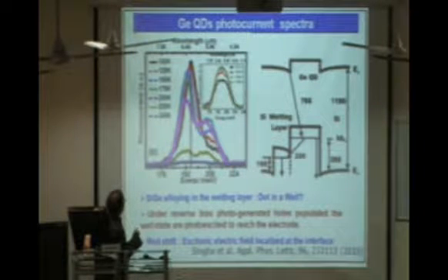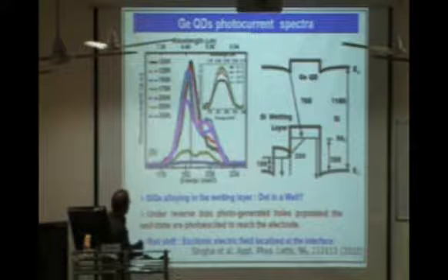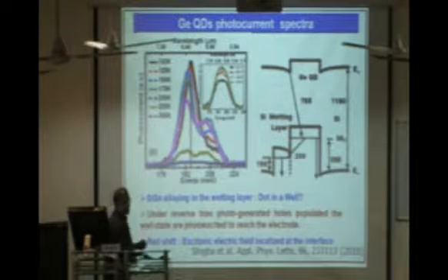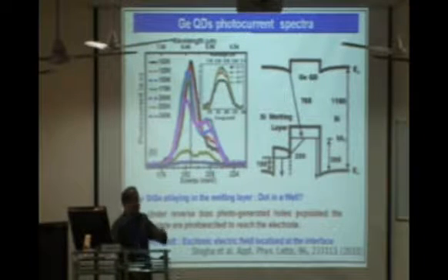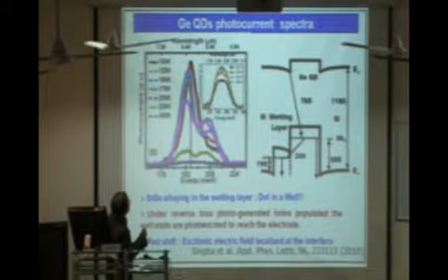And as you see, this works at room temperature because the leakage current of these quantum dots is very, very low. Of course, the noise is very high, but as you cool them, their photo response becomes very, very high, and this gives rise to detection. And this works at a very low voltage. Normally, a photodetector always has to be biased, but in this case, even with a bias as low as 0.1 volt, it gives a very good photo response.